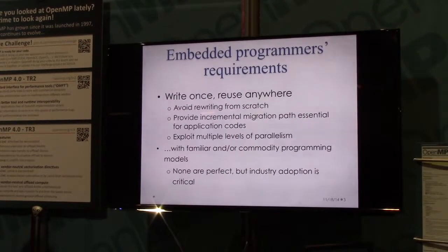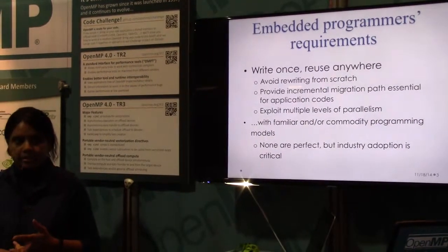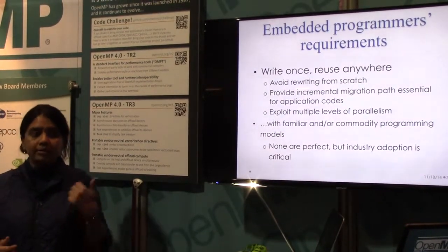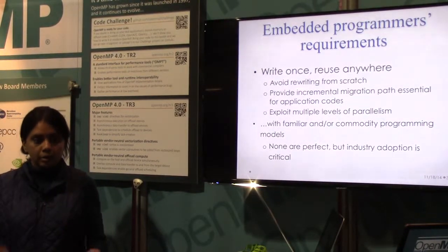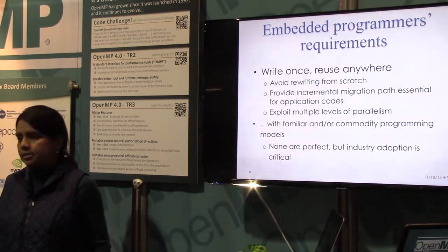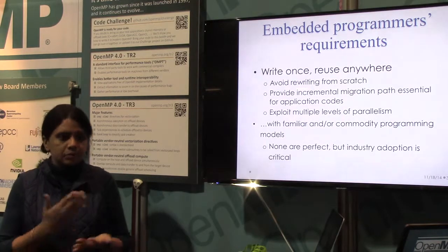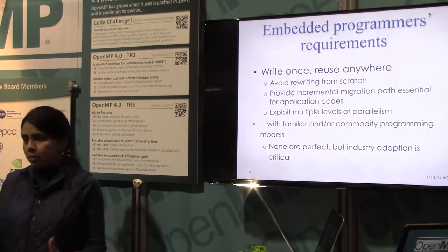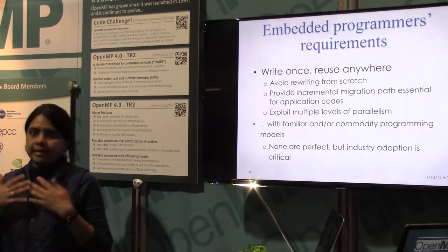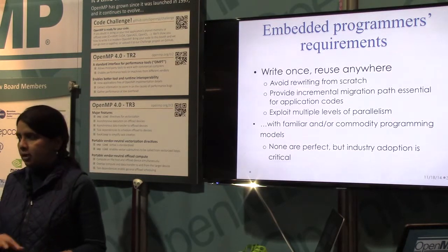And you have other devices like DSPs, you have ARM, you have FPGAs. So the problem is you try to program one particular device and you think your software stack is going to work on more than one device, and that's not the case. Even if you're using a device from the same family, like Texas Instruments, you take a board A, you have a program, you make it run on board A, then you have board A version 2 of the same company, and you still have a problem running your code on the device without touching it.